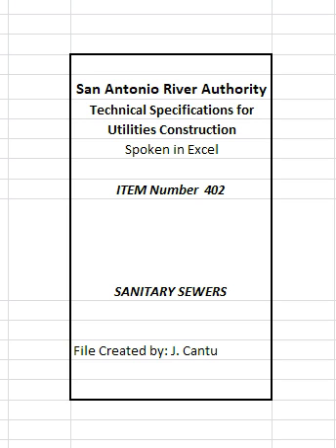A. Where a sanitary sewer parallels a water line, the sewer shall be constructed of cast iron, ductile iron, or PVC meeting ASTM specifications with a pressure rating for both the pipe and joints of 150 psi. The vertical separation shall be a minimum of 2 feet between outside diameters and the horizontal separation shall be a minimum of 4 feet between outside diameters. The sewer shall be located below the water line.